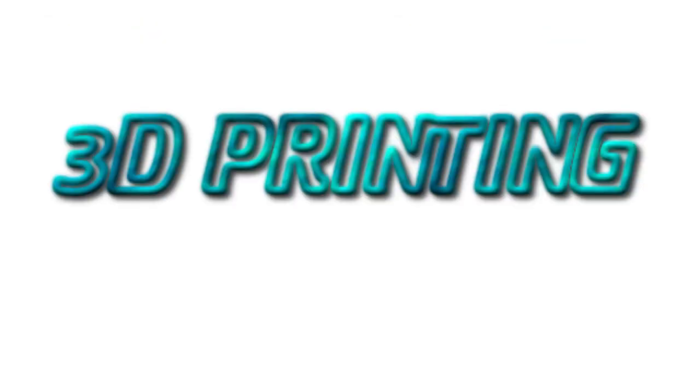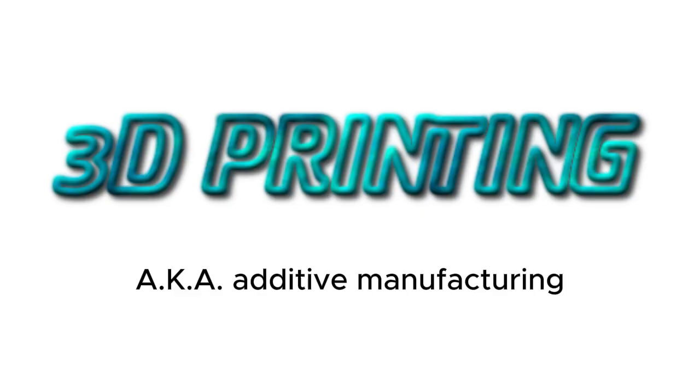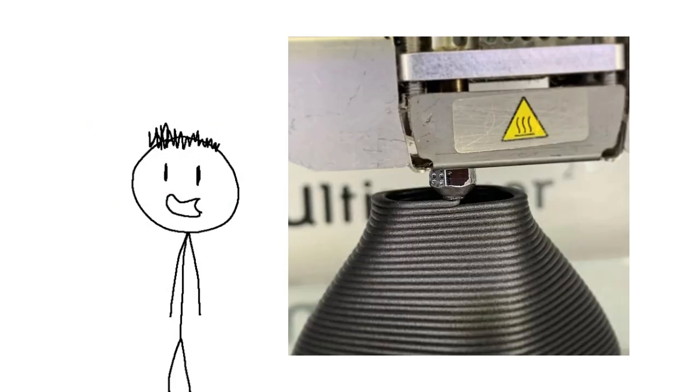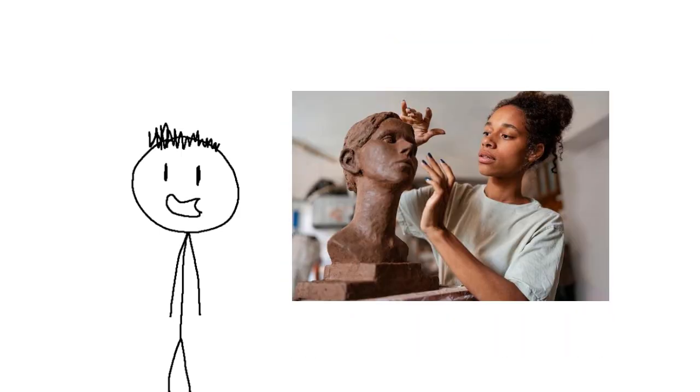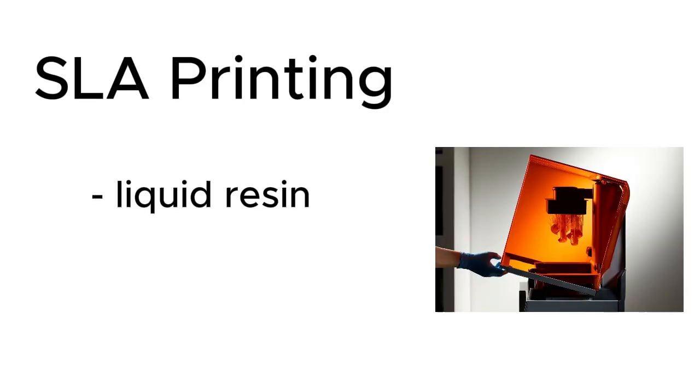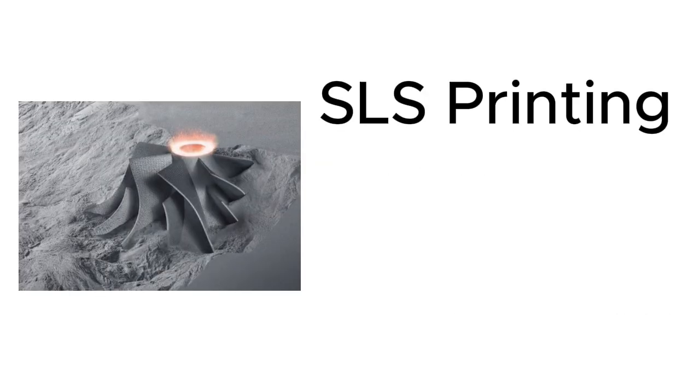3D printing, also called additive manufacturing, is a technology that creates objects by building them up one thin layer at a time. Instead of cutting away material like you would with woodworking or sculpting, 3D printing adds material only where it's needed. There are several types of 3D printing. SLA printing uses liquid resin hardened with a laser. SLS printing uses powdered material that gets fused together using lasers.